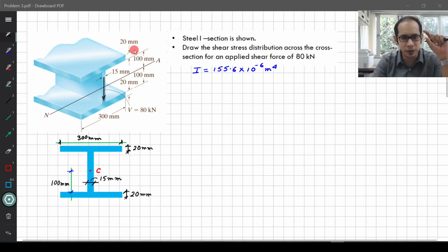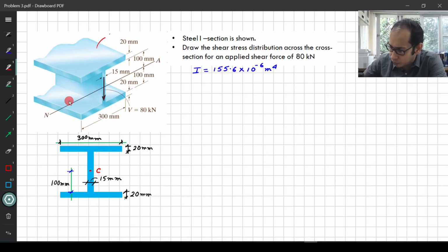It has sufficient width of the flange that you see over here. In eye sections, I am not sure if you are familiar with the terminology. This top part is known as the flange. This vertical part is known as the web, and again the bottom part is known as the flange. So let me maybe make a note of that. You will find this terminology useful later as well. So this is the flange, this is the web, and this part is the flange again.